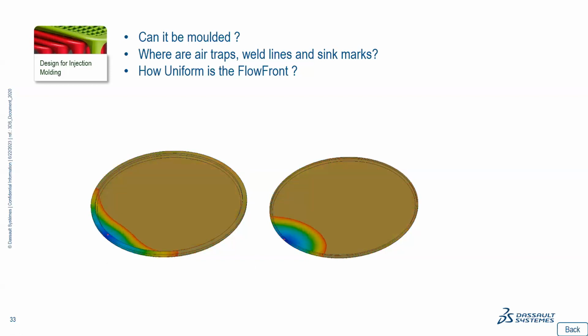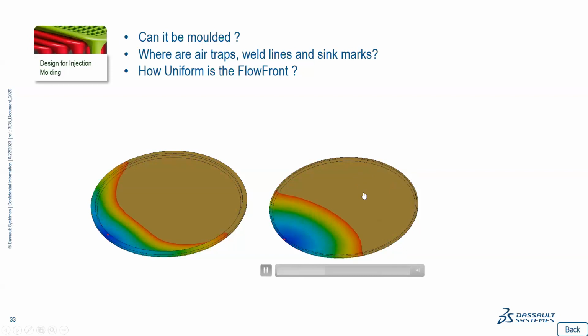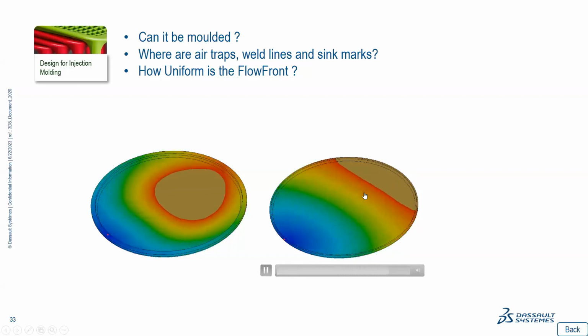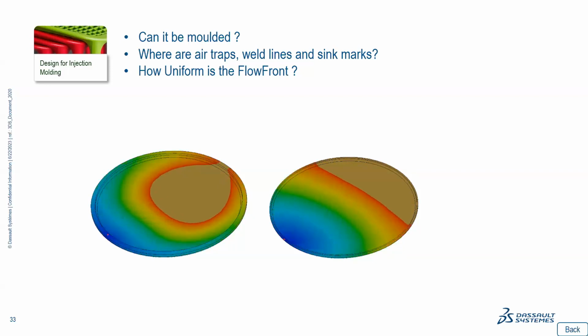So you will want to avoid this, because you can have some burn marks in your plastic materials, or directly have a part where you really have a bubble of air in your plastic material. So it would not be robust enough. So this is very important, to see how your design change can change the behavior of the injection.